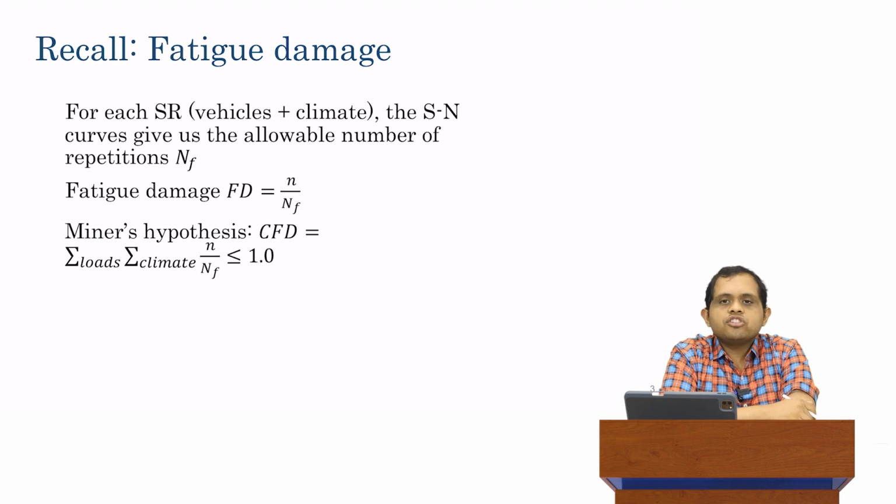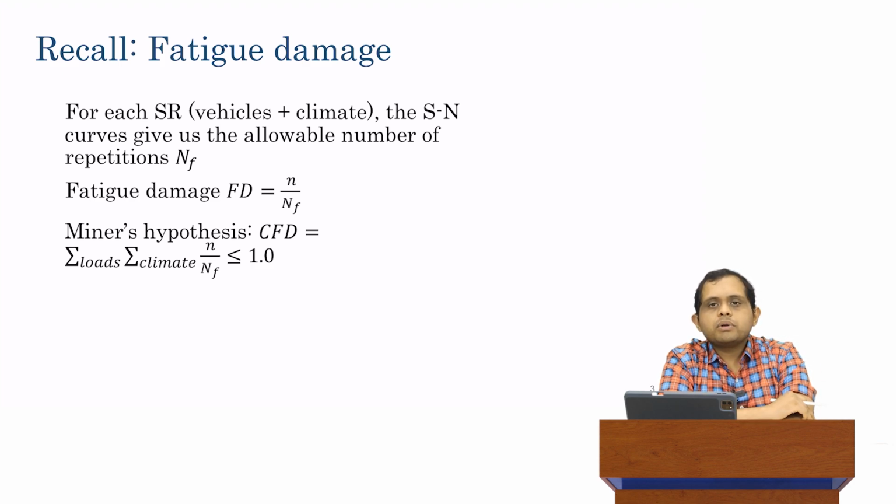Okay, so just to put a little mathematical juice in what I just described in the introduction. If you recall, in fatigue damage, we use fatigue theory to model rigid pavements. We talked in the previous lecture, and please review the previous lecture if you want more details, about how LRFD, load and resistance factor design, which is used in structural engineering, cannot be used in pavement engineering. If it's used in pavement engineering, it will give us the nonsensical result that the pavement should never develop any cracking or any type of distresses, which is not what we see in practice.